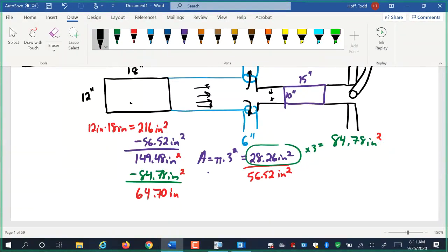So we might reduce that down here to a 5 by 13. So you can see what happens as we go down through there. And at this point, we've only got room to branch off 2, maybe 3 more ducts from that main duct before we've lost our back pressure.